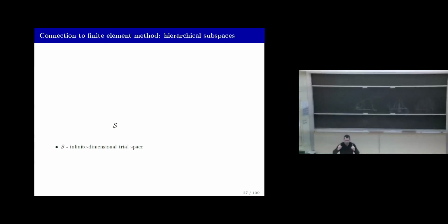So if you think about what the finite element method does, you pose your PDE in some sort of an infinite dimensional Hilbert space, and then when you do the finite element method, you search for solutions in some sort of a finite dimensional trial space. That's what you essentially do when you introduce your finite element shape functions or basis functions. When we do reduced order models, we take this one step further. I say, okay, sure, now I have a finite dimensional space. I can actually search for solutions on a computer in it, but it's expensive. It leads me to large models.